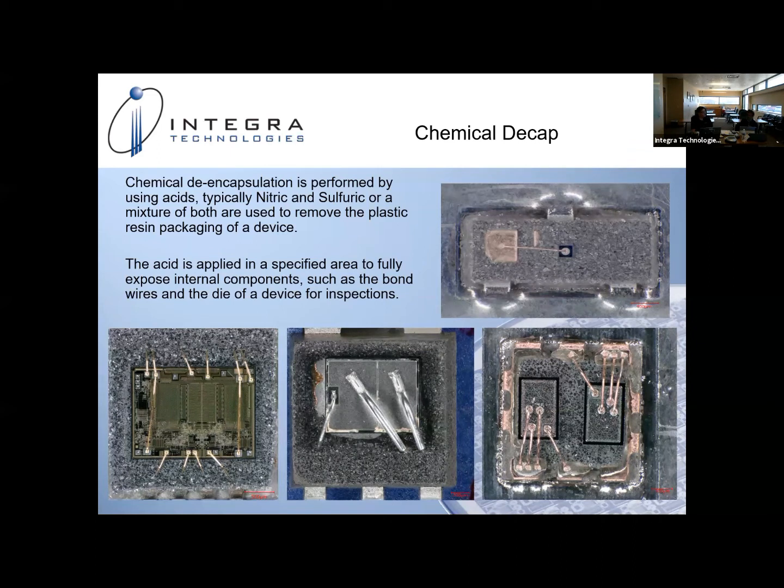Got a question? Yeah, it says, can you use chemical decapsulation for copper bond wire? Yes, and it's awesome to do that. However, it's an acquired skill. So if you have an extremely good lab technician who has done this kind of work day in, day out, yes. But